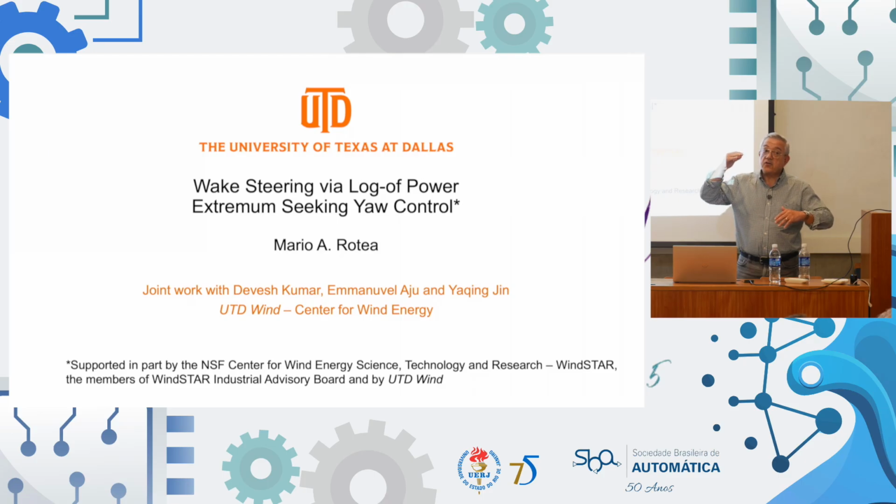It's not too high, so that we exceed the capacity of the generators, but it's in the middle, and that's called region 2. And that's the area where we want to maximize the power. Now, wind energy is about economies of scale. One turbine is not enough to connect to the grid and make money. Many turbines are, and that's why we have wind farms.